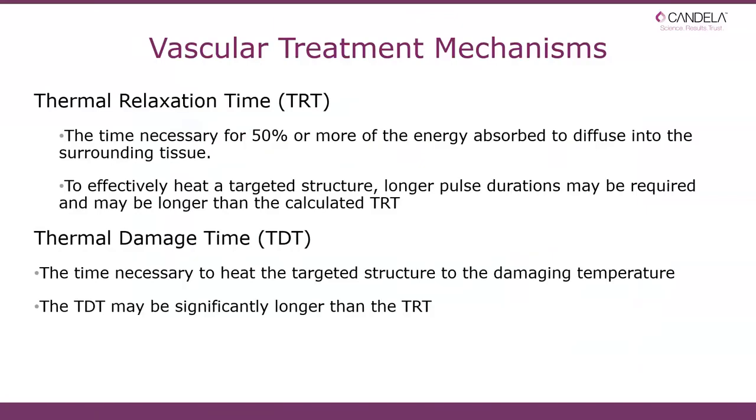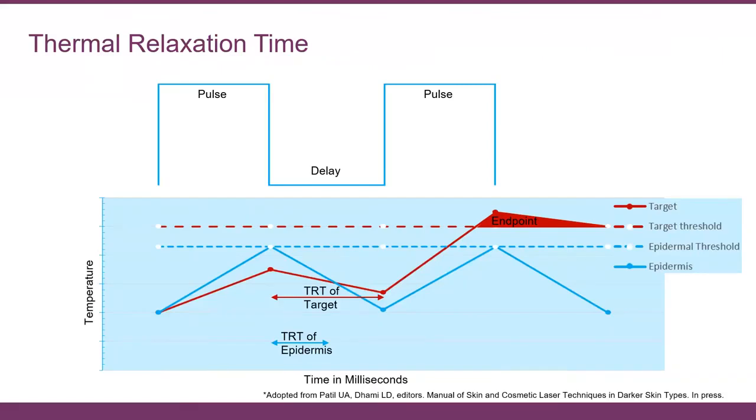The other point you have to think about is the thermal damage time. This is actually slightly different to the TRT in the fact that this is how much time is needed to actually heat whatever our structure is to a high enough temperature that we destroy it. And the thermal damage time is not always the same as the thermal relaxation time. In general, you may find that the TDT is significantly longer than your thermal relaxation time.